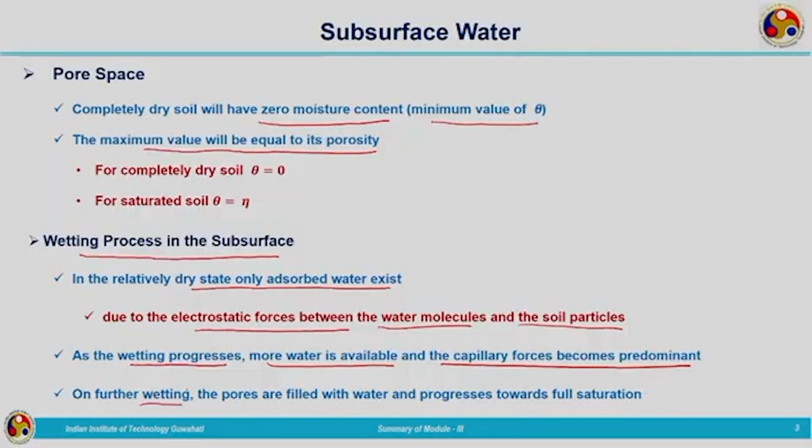After that, as continuous wetting takes place, all the pores will be filled with water and it will progress towards saturation. Initially it was relatively dry, then electrostatic forces were predominant, then as more water is added, capillary forces come into action. After that, the flow of water and the wetting process continue. At that time we have saturation and gravity force will be predominant.